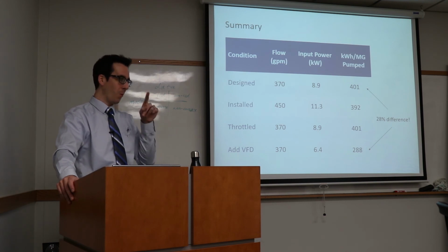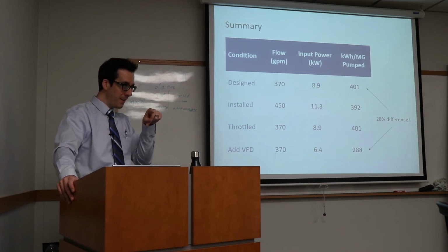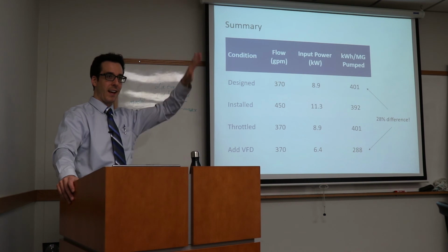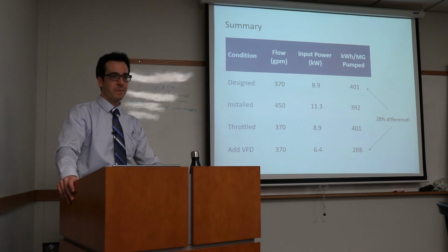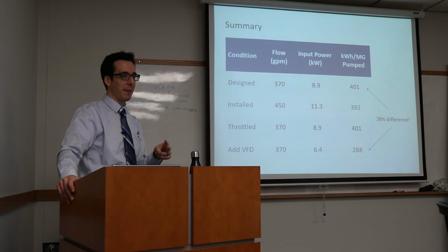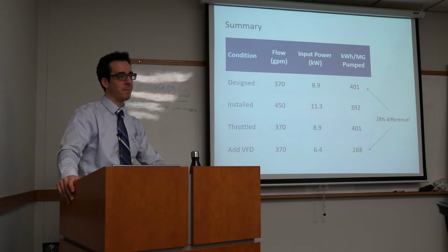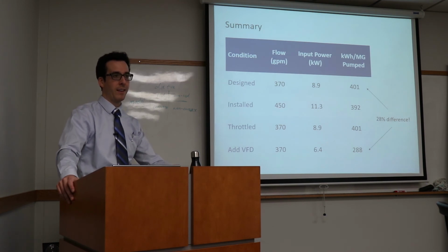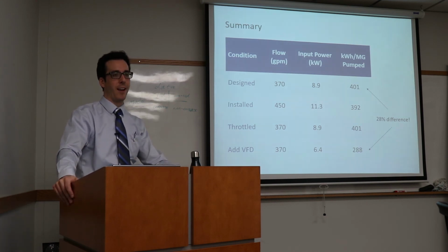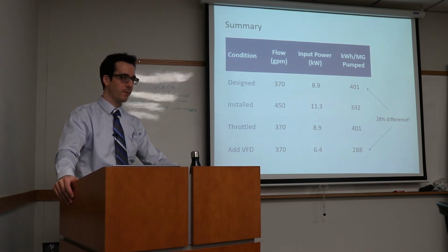But one pump running at 1,000 GPM in parallel with another one doesn't give you 2,000, does it? Because there's more friction involved, because that curve goes up. If you have two pumps that each produce 1,000 GPM by themselves and you put them both together, you might only get 1,500 or 1,700 GPM. You might not even get that much, depending on the ability of the downstream distribution system to accept that kind of flow with minimal head loss.